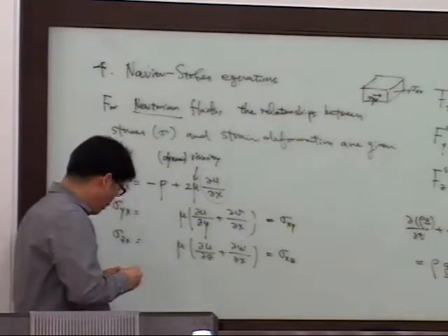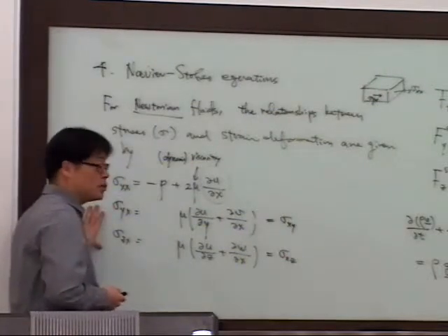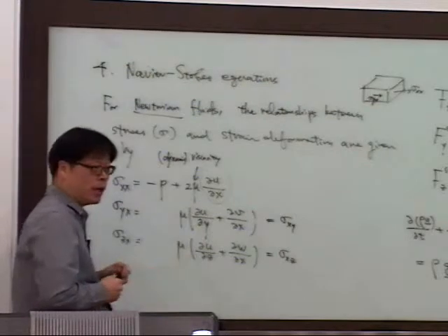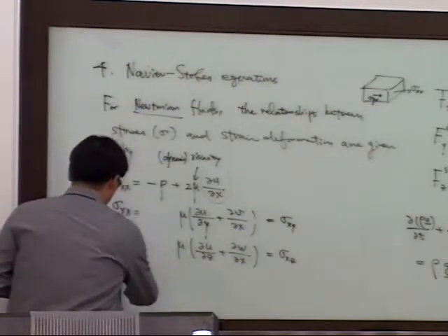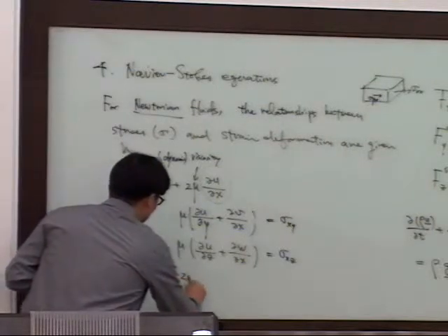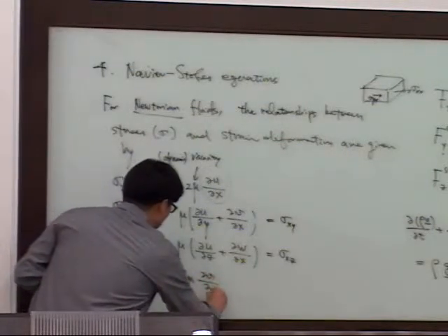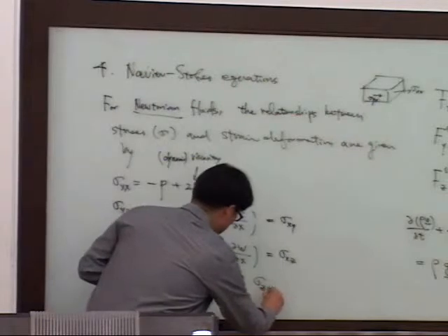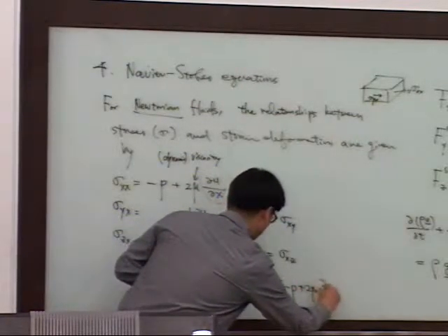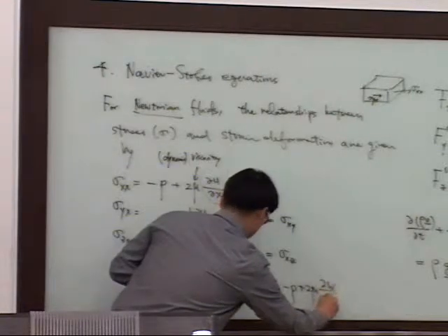But for water, this is a very good approximation, and we represent stress in terms of velocity in this way. And likewise, the y component is minus p plus 2 mu dv dy, and sigma zz is minus p plus 2 mu dw dz.